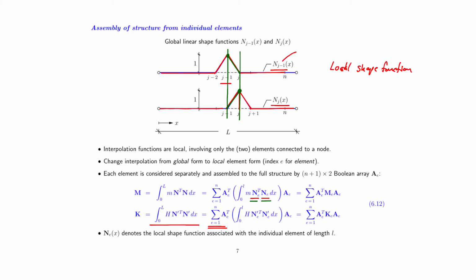and that means we have just as many different interpolation functions as we have elements, and we will then derive an element stiffness matrix and an element mass matrix. And then we will simply place these matrices at their appropriate locations in the global mass and stiffness matrix. And that we will demonstrate. Mathematically speaking, we can simply write that up by a transformation matrix A that is multiplied onto the local matrices from front and back, and this transformation matrix could as well rotate from a local to a global coordinate system. But otherwise, it's a fairly simple Boolean array.